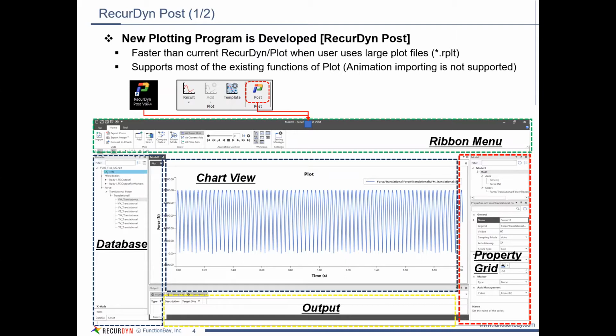So we do encourage all of you with your RecurDyn models to use the plot multiplier factor and to generate lots of plot points, because when you have abrupt dynamic events, to have an abundance of plot points makes it better for you to understand that dynamic event.